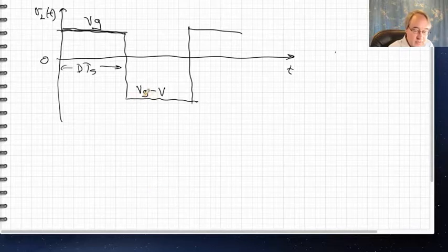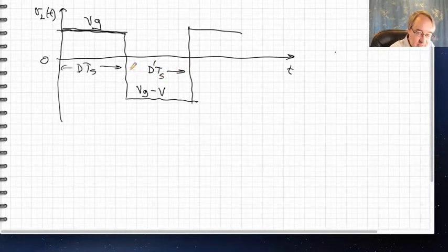And you can see that since the voltage has to be negative to get the volt-seconds to balance, V needs to be bigger than Vg. So therefore this is a boost converter, where the output voltage V is bigger than the input voltage Vg, and volt-seconds won't balance otherwise. So this is during interval d', the second interval of length d'Ts. That's our inductor voltage waveform.